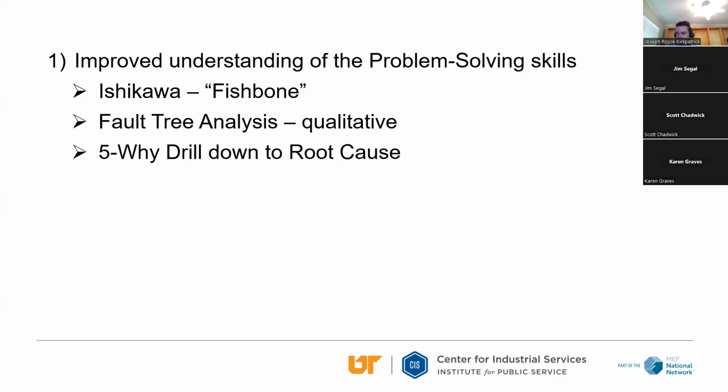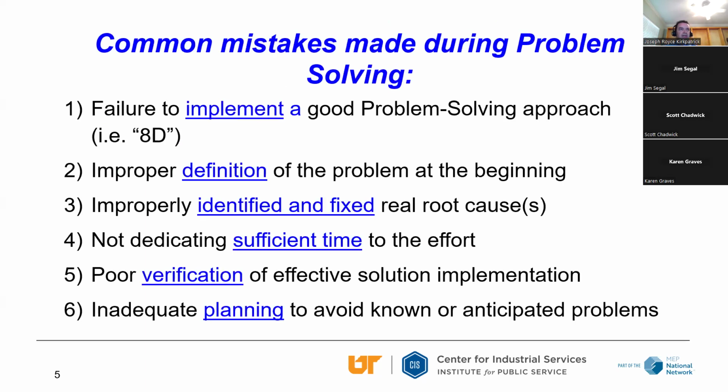But Ishikawa fishbone diagrams are good to help facilitate the problem solving process. You could do a fault tree analysis, or most of the time in the automotive world anyway, we use a 5 why to try to drill down to the root cause or root causes of the problem.